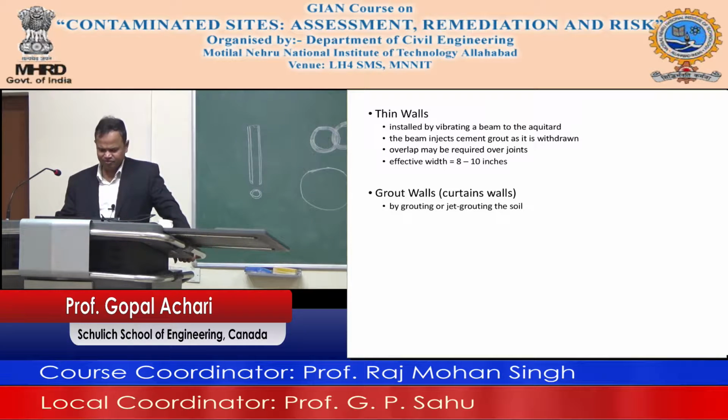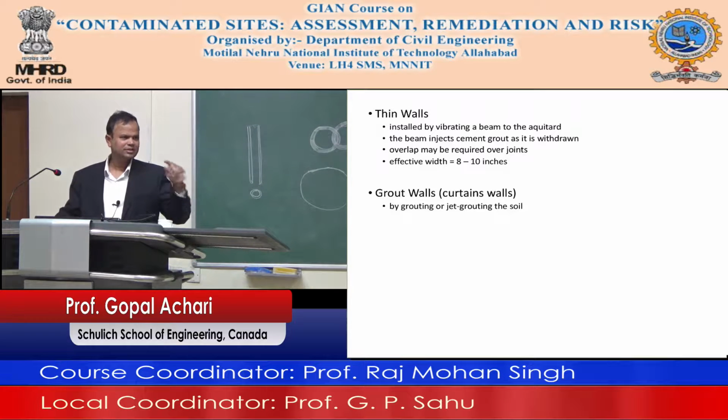Okay, so you have 2-3 feet of compacted clay. Follow this diagram here. A few feet of compacted clay. On top of it is a 60 mil HDPE liner, high density polyethylene liner. This is plastic material. Okay, it's not plastic, but it is a similar material. This blue thing here.